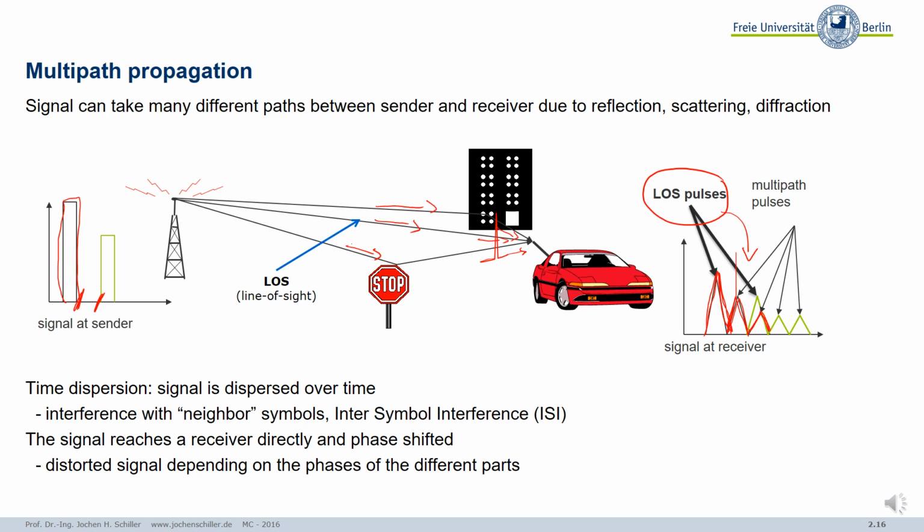Now just consider you walk down a road and, well, you don't see the base station, and you can imagine how many of these multipaths you have. Yes, it's an infinite number, but so many different ways of reflection, and there's some refraction, multiple reflections, so it can be a kind of a zigzag pattern, some multiple reflection between buildings, etc. And the more reflection you have, the longer the path is, and the more the phase shift is. And somehow your antenna has to handle this.